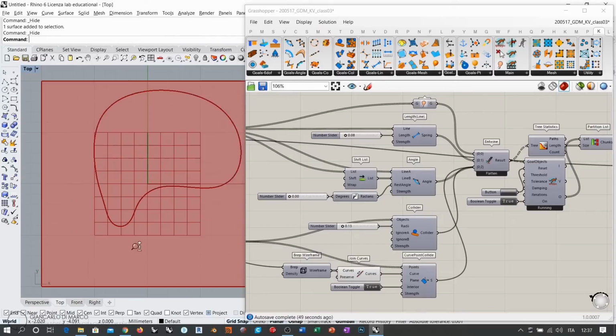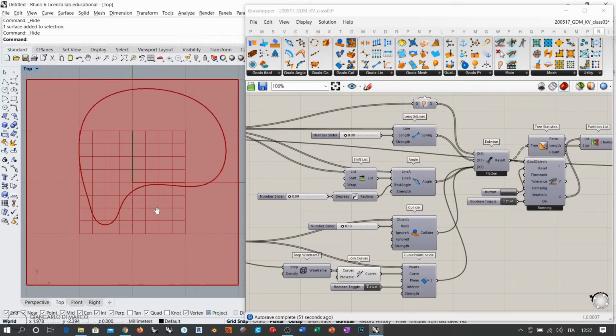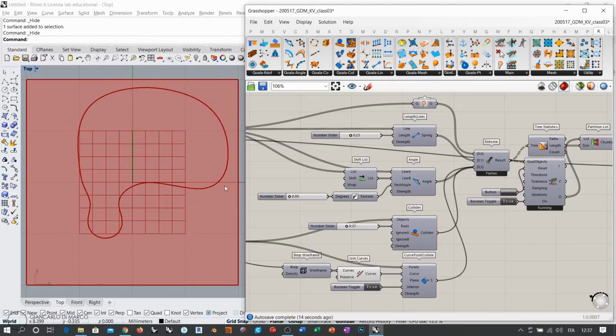In order for this to become visible again, I must increase these values here and make their action stronger than the resistance of the smoothing that we are creating right now. Increasing these two values will tend to expand the curve, as we know, but this acts like some resistance to the deformation. This curve is already expanding, but you no longer see that kind of vibration during the expansion.